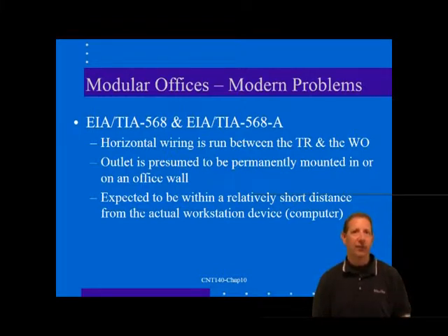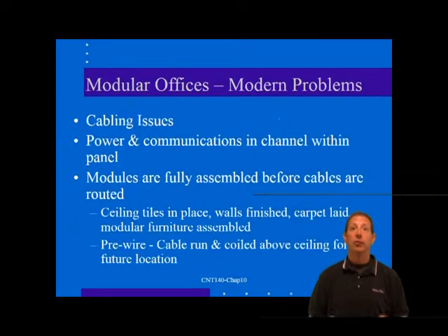And in many instances, the relatively delicate fiber and copper cables are the wrong length in the new arrangement and cannot be reused. The only option in such a home run environment is to pull an entirely new cable to each relocated workstation. At an earlier time, this was the only approved method to run and rerun standards-compliant Category 5E and higher links, as the standard allowed no splices or intermediate couplings.